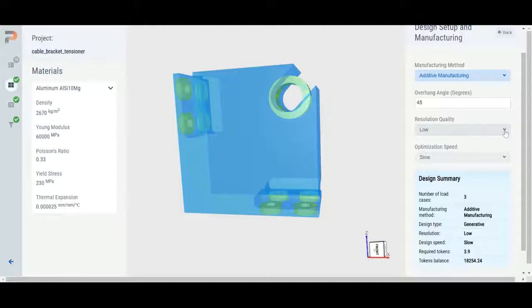We select the next step, the resolution: low, medium, high. Resolution means the finite element discretization. We always suggest to users in the first step to run a minimum compliance problem and also to run a low volume fraction in order to see that the design setup is correct, because low resolution runs faster and the design can be achieved much quicker and at lower cost.